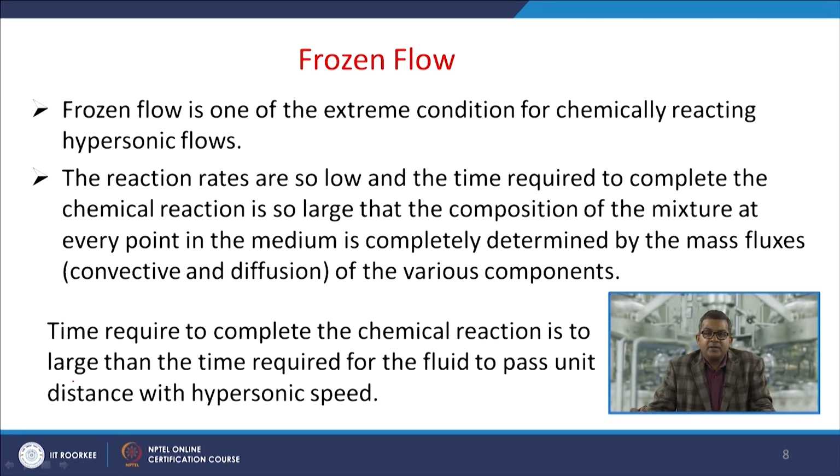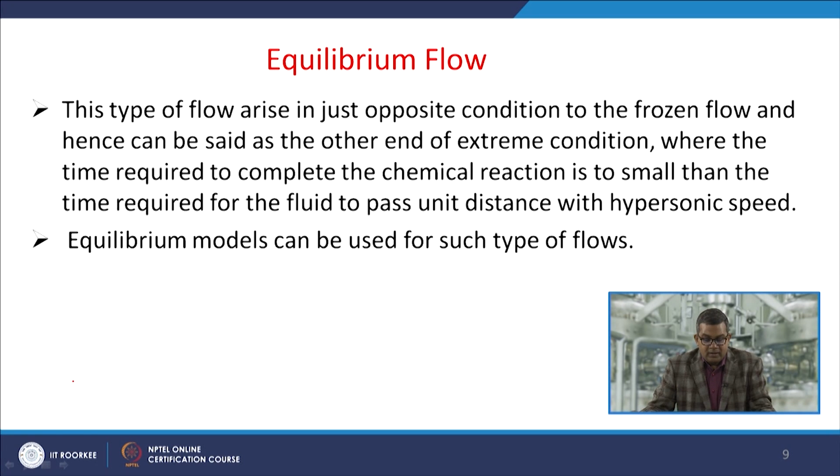First let us take frozen flow. Frozen flow is one of the extreme conditions for chemically reacting hypersonic flows. The reaction rates are so low and the time required to complete the chemical reaction is so large that the composition of the mixture at every point in the medium is completely determined by the mass fluxes, both convective as well as diffusive. The time required to complete the chemical reaction is larger than the time required for the fluid to pass unit distance at hypersonic speed.